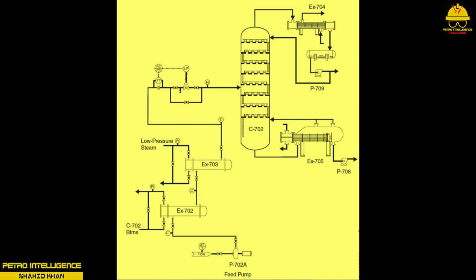During startup, cold feed is sent to the column at 50 GPM to allow the steam heating systems to be engaged. As cold feed enters the column, it drops from the feed tray to the bottom of the column. The bottom outlet line feeds a kettle reboiler located at the base of the column. As the level rises in the column, it simultaneously rises in the reboiler.